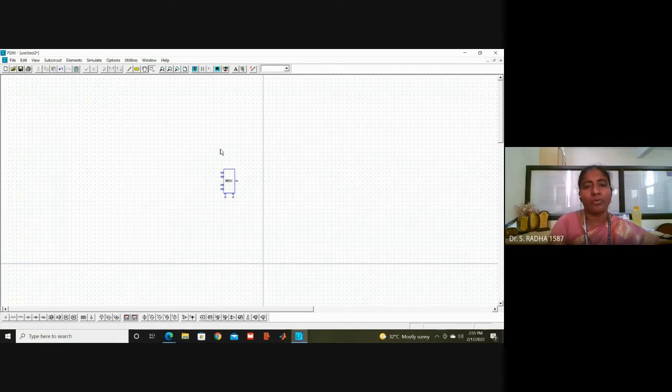Okay. Now 4 inputs are there, 2 selection lines are there. So that many square waveforms I want, and keep them appropriately without overlap. Here I will keep the first voltage. Okay, second voltage, third voltage, fourth voltage, selection line MSB, selection line LSB. Okay, give escape. Take the ground connection, give ground for all these voltages, ground connection for all the voltages.